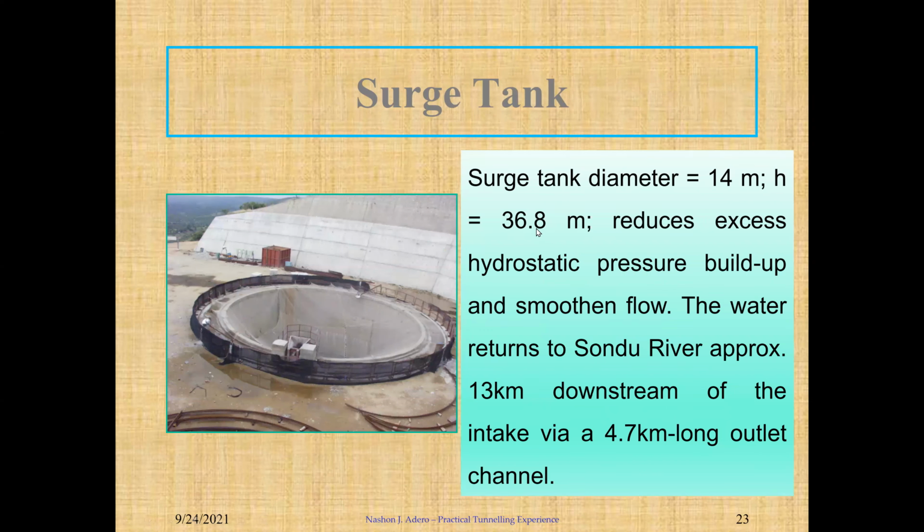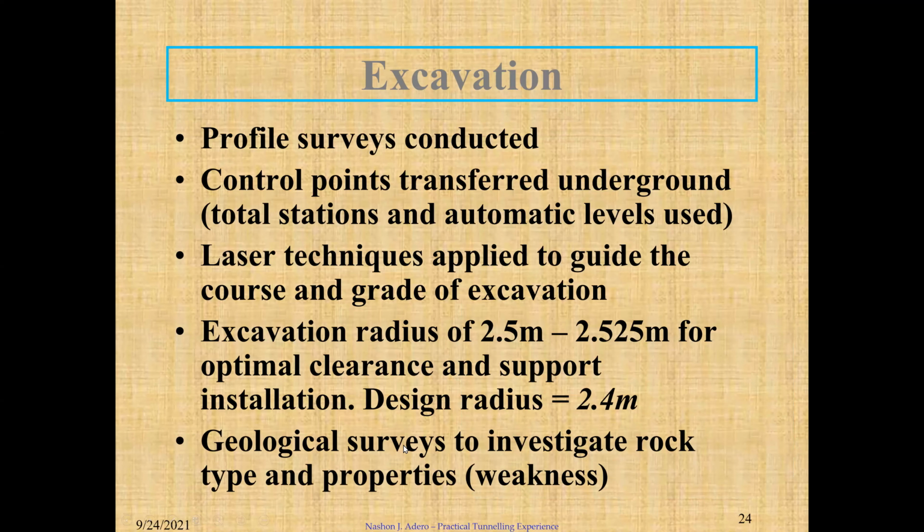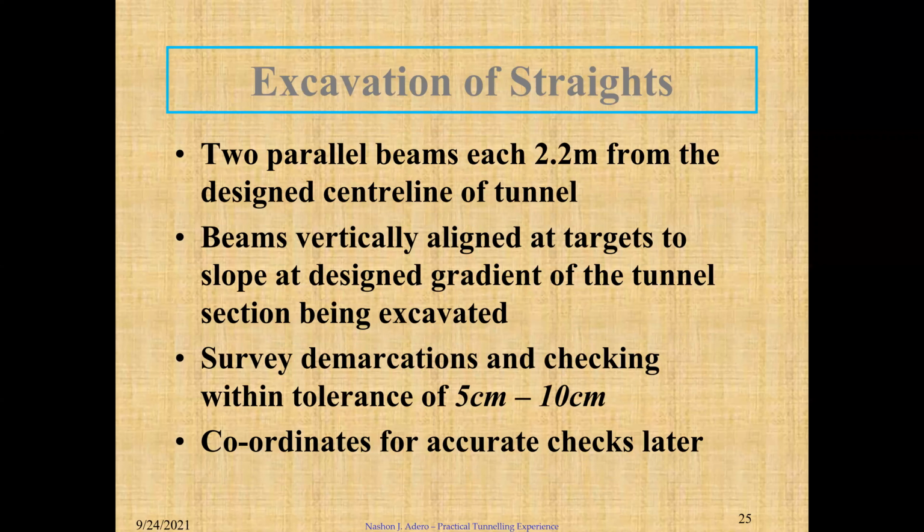Surge tank, which I said the depth is more than 36 meters. This is now at the downstream end. So during excavation, laser techniques are key. Why laser? Because when you are underground, a laser beam gives you a very sharp line of sight.